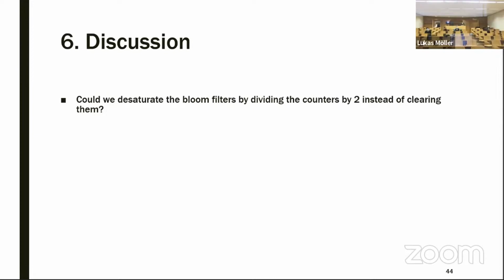Right. But then you would do it one after the other, and it would mean an additional latency cost, I guess. Yeah, but you have enough time to do that because, as we discussed, each lookup only takes about 1 nanosecond, and a DRAM activation takes about 50. So we have 49 nanoseconds of extra time that we don't really know what to do with. Yeah, okay, then that could actually make sense.